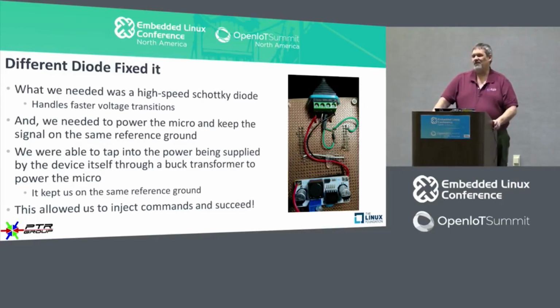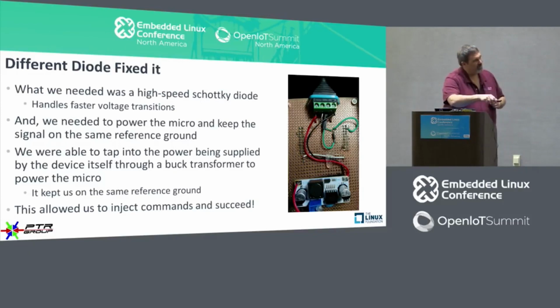So if you powered the microcontroller through a 5 volt USB connector, everything worked fine. If you powered it with 3.3 volt, it didn't work, at least not for our application. So we basically took the 9.6 volts, we pulled the power off of the connector, we ran it into this power supply, we then ran the power supply underneath into a USB adapter, which you can get from SparkFun.